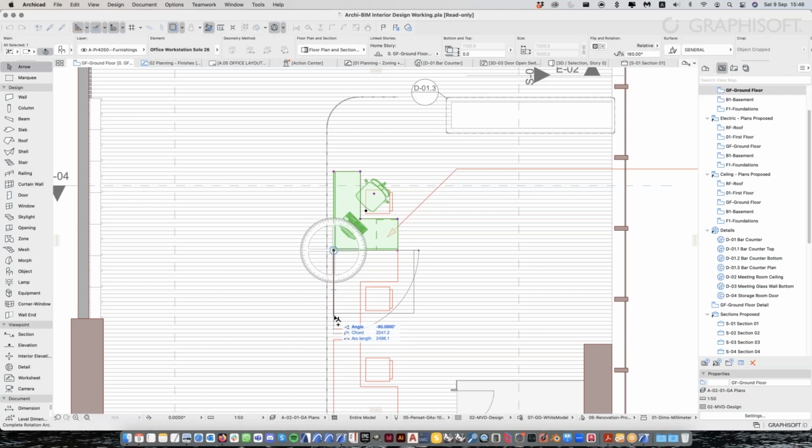So if you do want to type in the angle, you see this blue box here. When you move around, it shows a blue box. You just need to press Tab, then it will jump to the first line of the blue box. And ArchiCAD counts the angle from this way. So the positive is going this way, the negative goes this way. So if I want to rotate here, it's actually -90. So I just need to press Tab, -90, and click Enter.